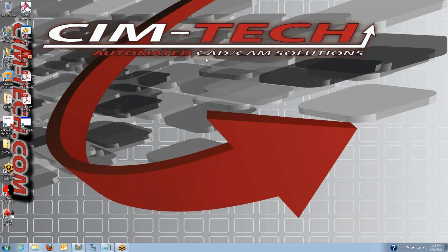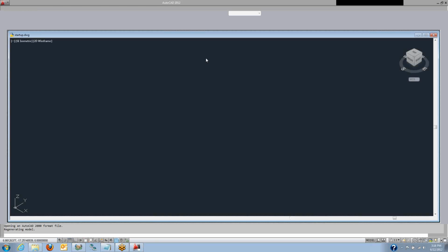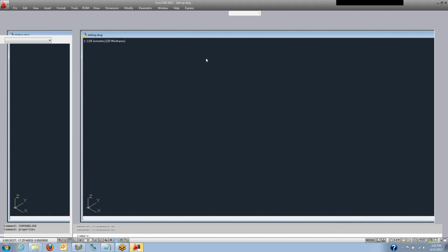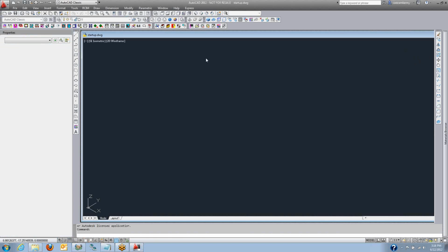And we use the AutoCAD material. So when you use the AutoCAD rendering materials, for example, you can specify different materials for your parts. Those will be the materials used in Router-CIM. Same thing with Inventor. We use the materials from Inventor. We also use the part names from Inventor. And you can specify the part names in AutoCAD solids as well using the properties.